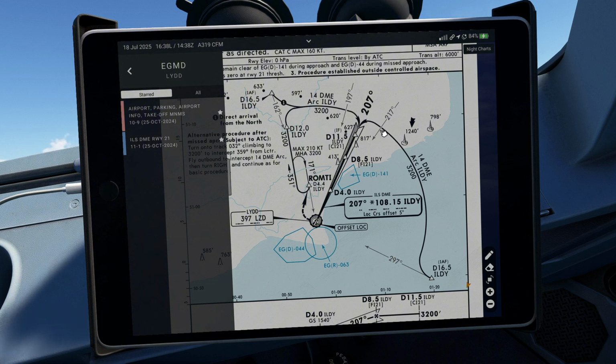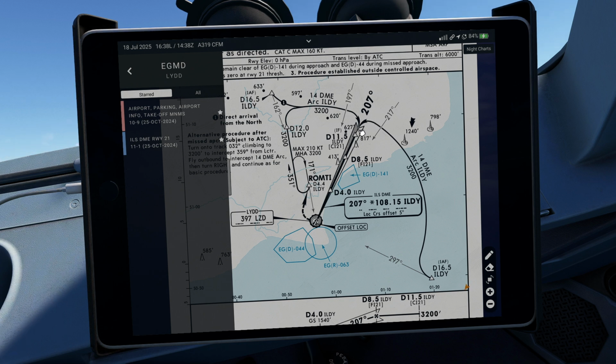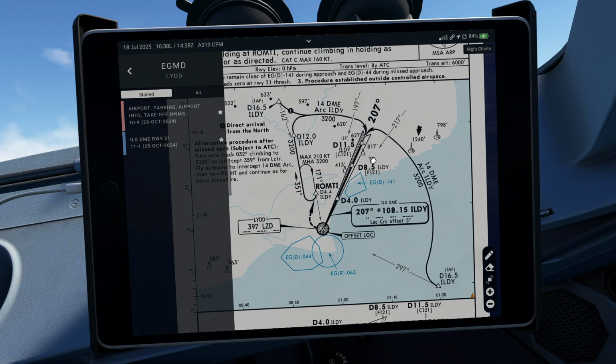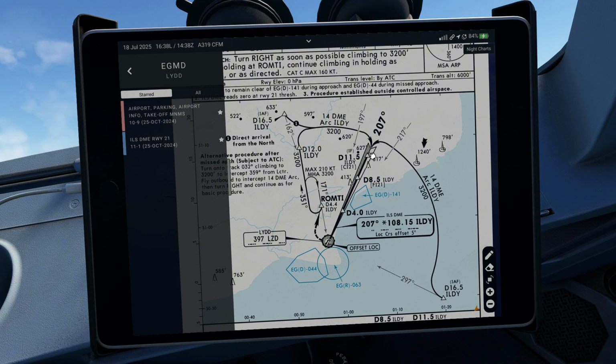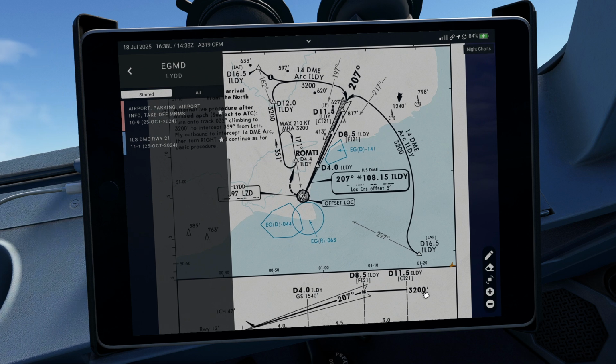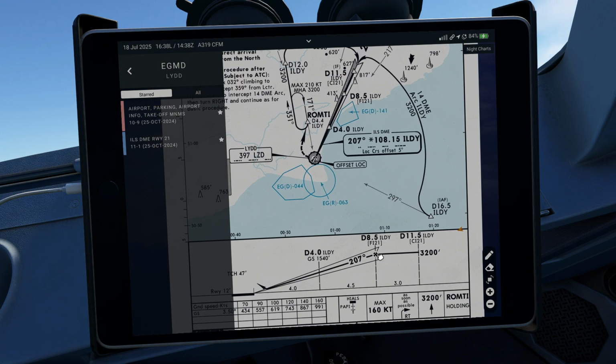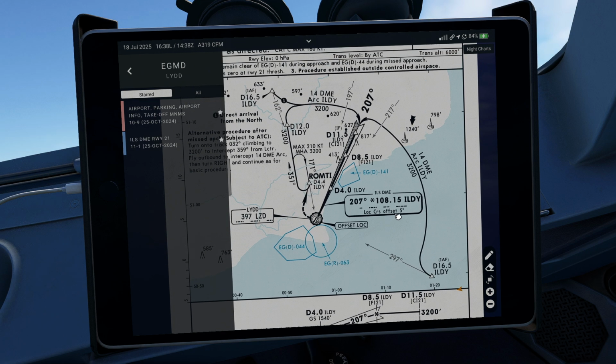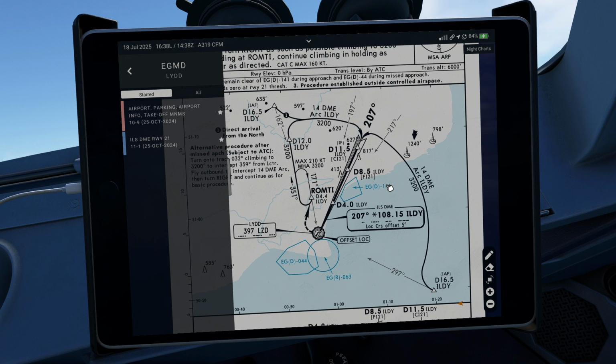When passing the radial 037, which is a lead radial, we will commence the turn to the final approach course 207, descending down after reaching the final Foxtrot India 21, which is the final approach point, down to the runway with a 5 degrees offset angle.